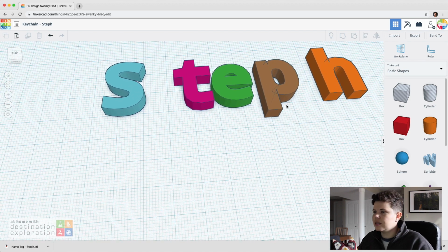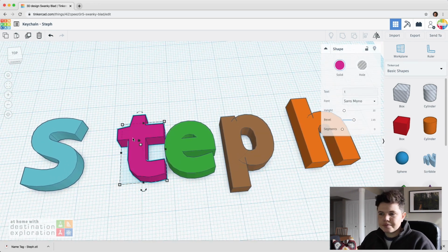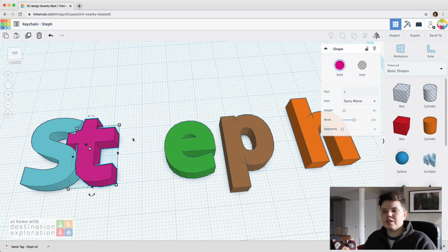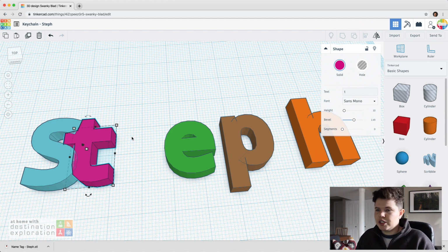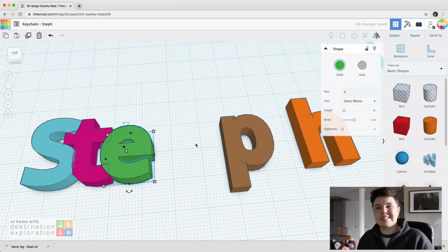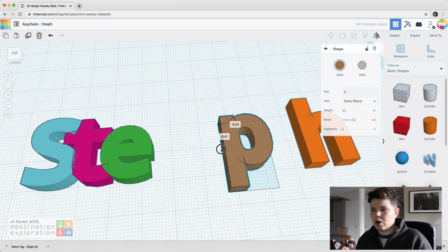So all I'm going to do is zoom in here. I can use the arrow keys, or I can click and drag. When we use the arrow keys, we're actually just bumping, which means that the objects aren't going to go up or down or move in a way that we don't want them to. We do want to make sure that they are sticking together. We do have some overlap because, again, when we're 3D printing, we want it all to come out as one.